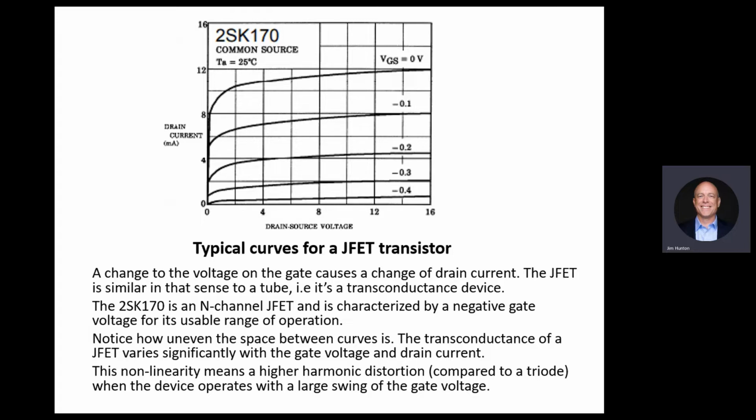Negative feedback is what everybody's talking about. So you say, well, if it generates harmonics, we'll bring them back, subtract, we distort the input signal, and we'll fix the output. Yeah, you can do that. There are consequences to that. So ideally, you want to start with a very low distortion device, and fix it if you need to at a minimum level.